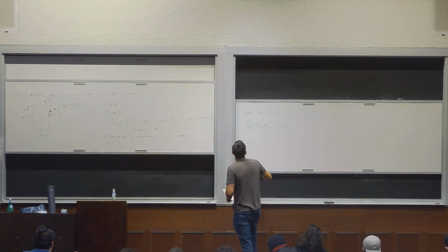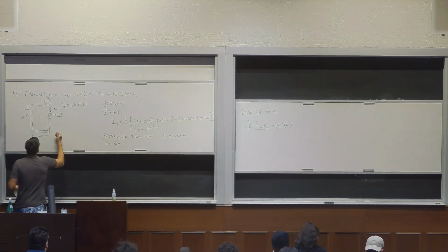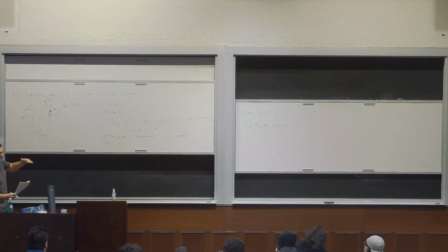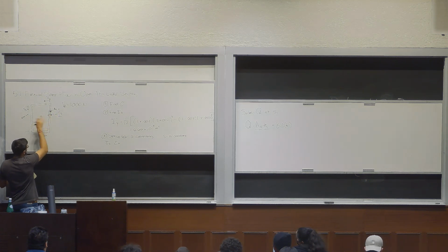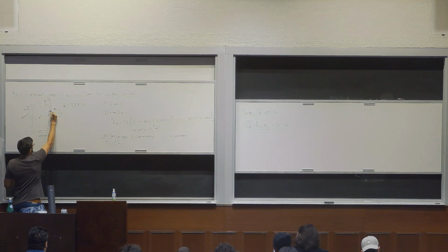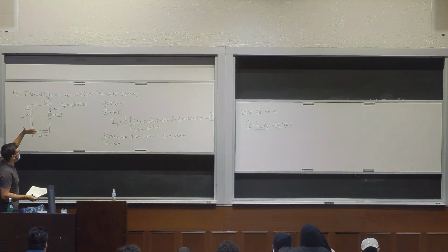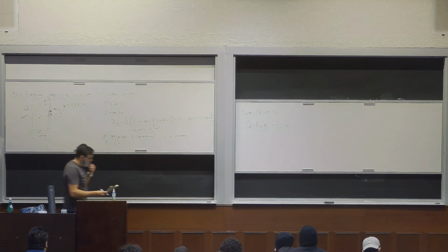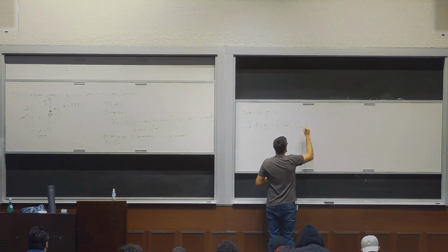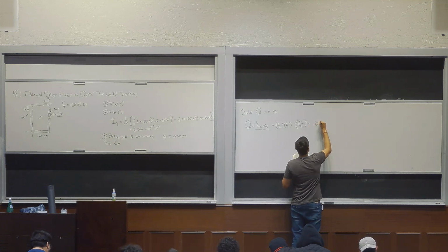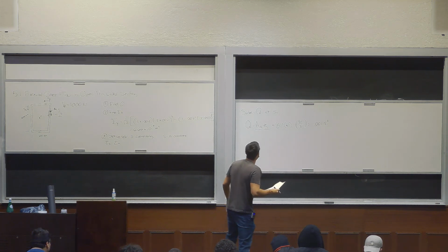Now we're interested in finding the Z position of the centroid of that area. It's just a rectangle, so the centroid's at the half of the height. So this is the centroid here, not the centroid of the original structure, the centroid of this location. It varies with S. As S increases, it's always going to be S1 over 2. So I'll just write that down: 0.001 S1 squared. Okay. Now we know Q.